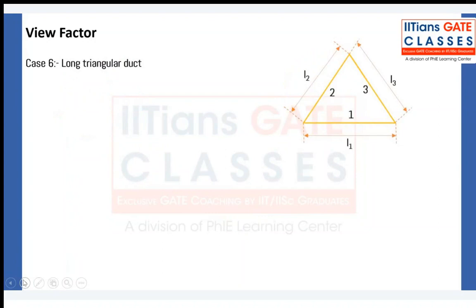Now this is a long triangular duct. You need to find out certain things, but tell me one thing. What is F11? Yes, it is 0. Tell me what is F22? Yes, whenever a plane surface is there, the radiation emitted from that plane surface and received by itself is always equal to 0. F33 is also equal to 0.